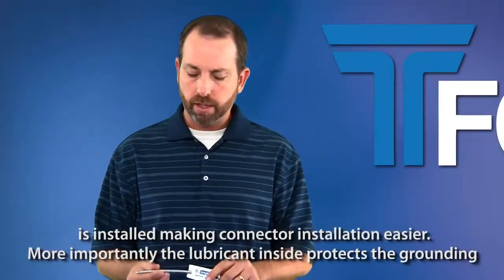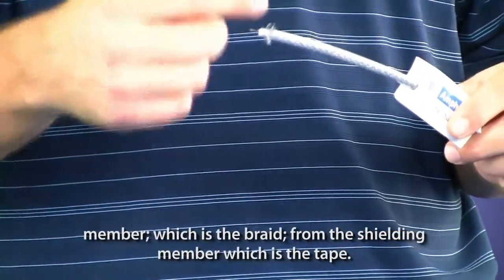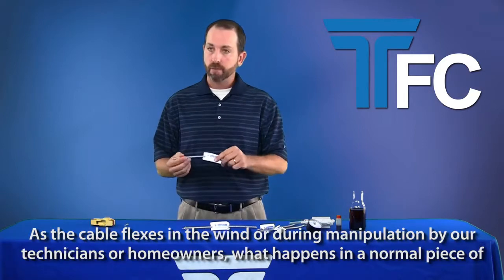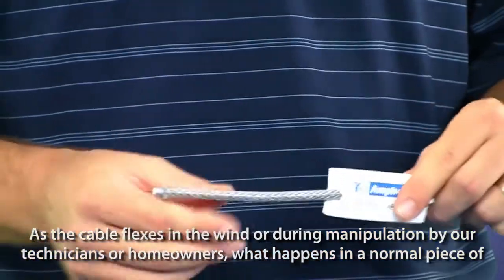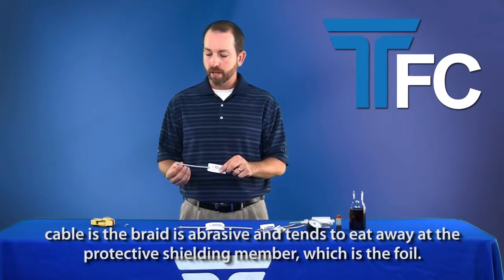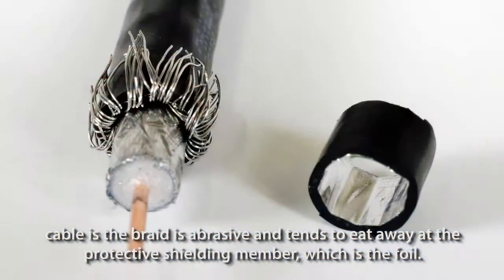And even more importantly, the lubricant inside actually protects the grounding member, which is the braid, from the shielding member, which is the tape. As the cable flexes in the wind or during manipulation by our technicians or homeowners, what happens in a normal piece of cable is the braid is abrasive and tends to eat away at the protective shielding member, which is the foil.